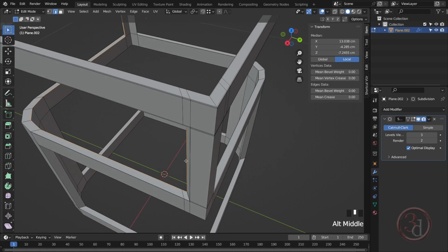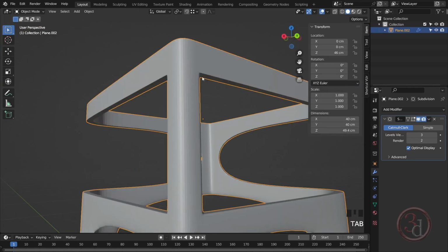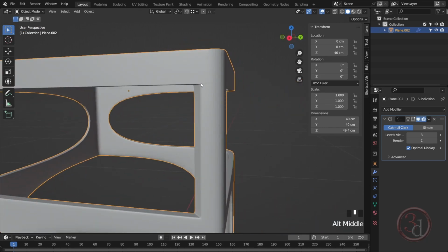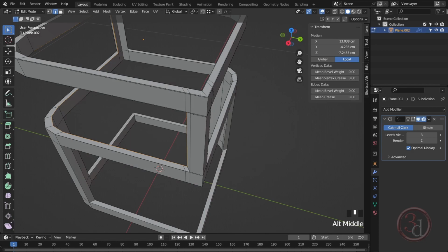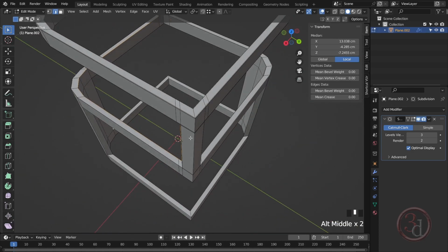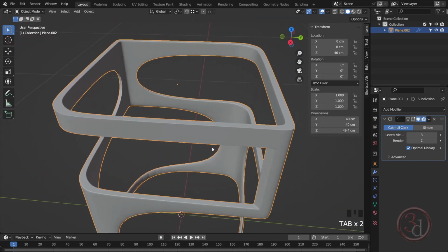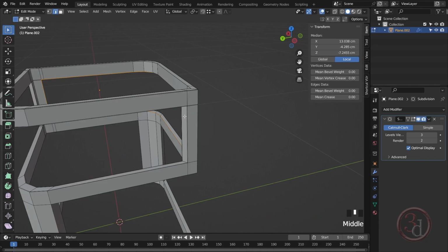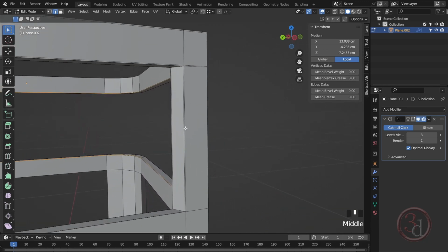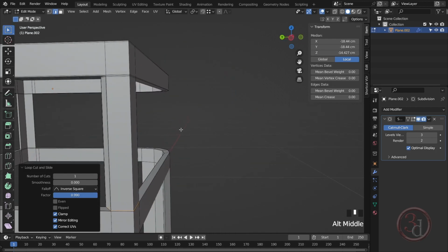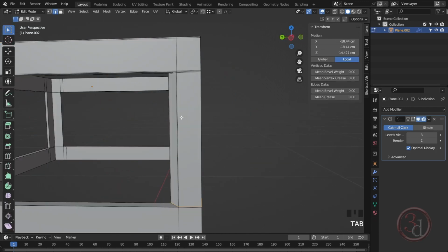All right. And I can add further in between to reduce this slight line that you see coming over here. I can reduce it by adding more over here, but I will not do it at the moment. So let's continue. And then I will come over here and do the same thing. Press Ctrl R and move it all the way up. Yep. Press Ctrl R and move this all the way down. And press tab. Yeah, good.